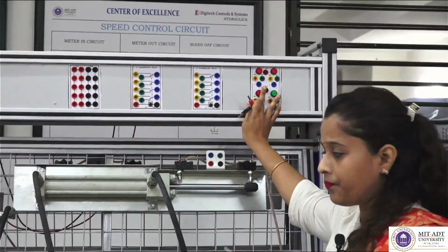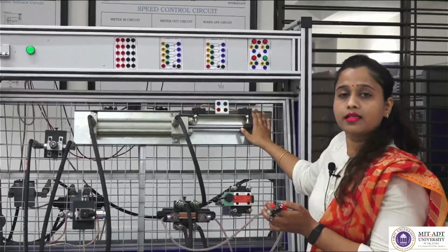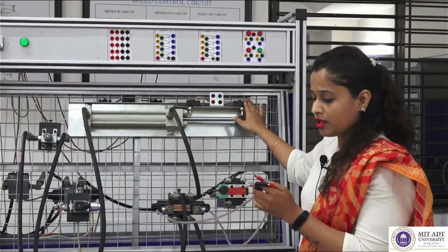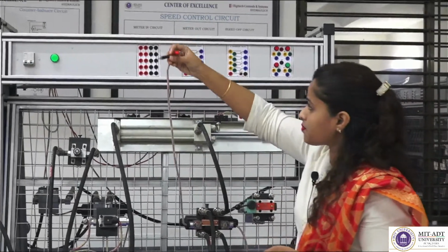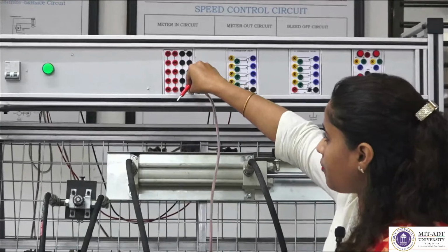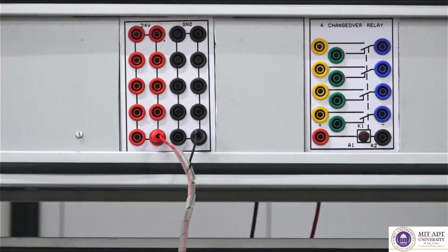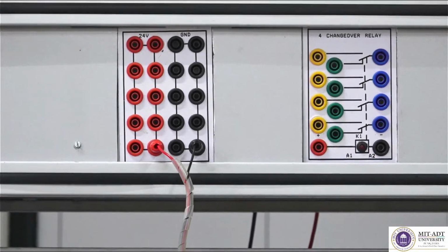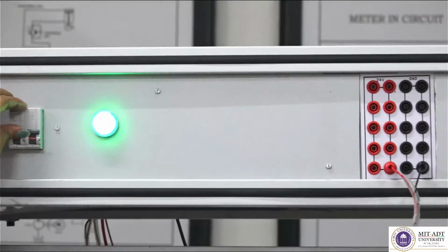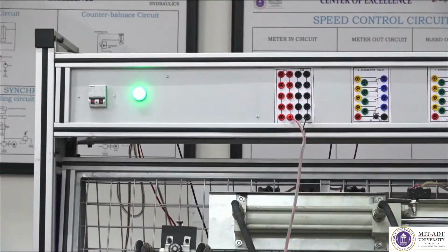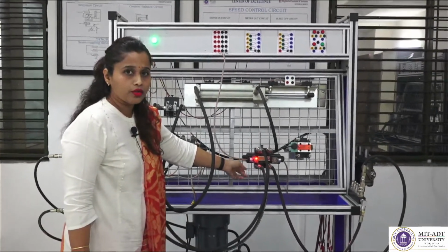Let us now see how we can give a signal to this solenoid in order to operate this double acting cylinder for its extension as well as retraction stroke. What I am doing is, I am taking this black color wire of this side solenoid, giving it a ground and giving it a 24 volt supply. Right now, I am giving a supply to only one side solenoid so that we can see how its operation goes ahead. As my whole setup is in a working condition, here you can see that I have given electrical supply to this solenoid.